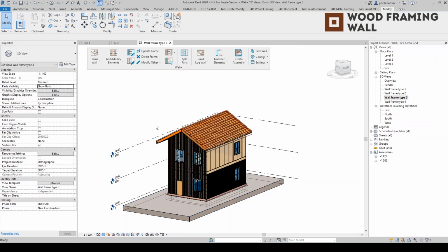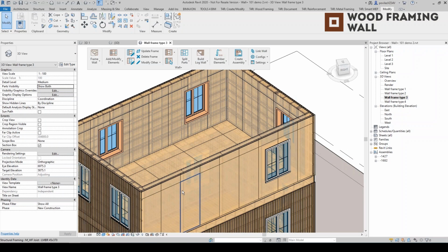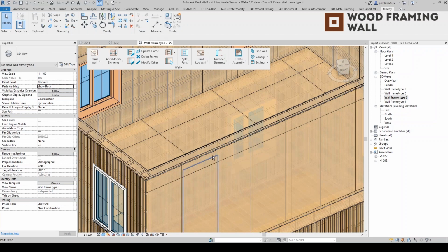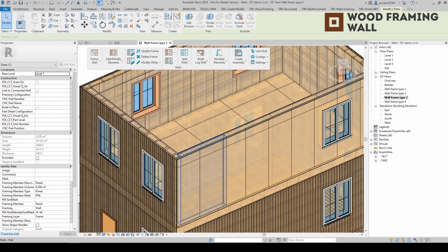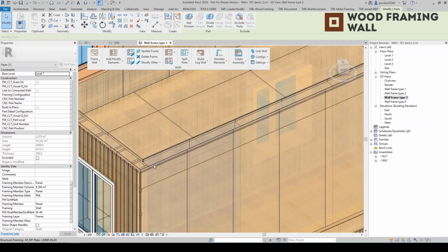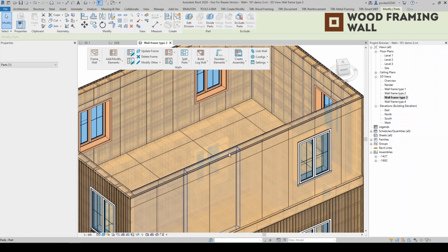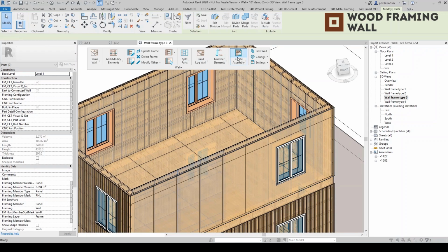Okay, again, why I did switch to both. Just for clarity, I'm going to drop down scope box. Okay, and as you see, by splitting parts, I've managed to get my exact dimensions that I defined in the configurations panel and configurations here. So I get exact dimensions of each prefabricated wall panel. So what they are missing, actually, they are missing actual frames.